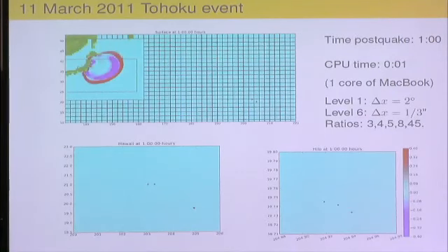And the grid that you see here is a coarse grid over the Pacific Ocean. Hawaii is where these dots are here. This is a zoom on Hawaii that at the moment looks pretty boring, but as we add more refinement, you'll see that come into focus. So we have one very coarse grid here where the grid spacing is 2 degrees, which is about 220 kilometers on the side. We use ultimately 6 levels of refinement to zoom in to Hilo Harbor with a resolution of 1/3 arcsecond, which is about 10 meters on the side.